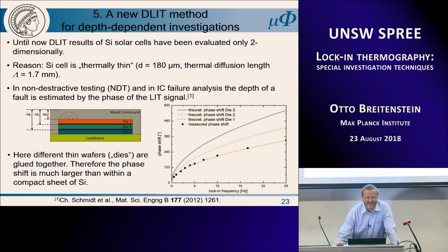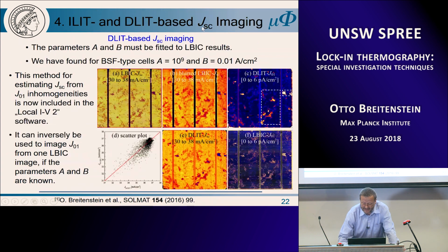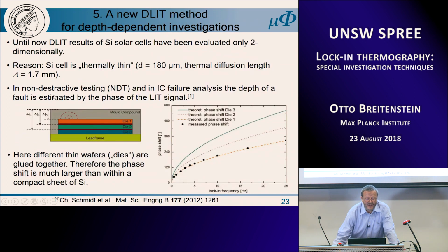However, in non-destructive testing and integrated circuit failure analysis, where lock-in thermography is also widely used, there is a method. The depth of a fault can be estimated by considering the phase of the lock-in signal at the surface. And this is being done here on these multi-chip devices.